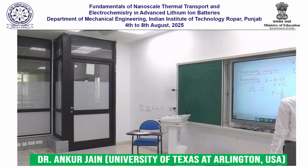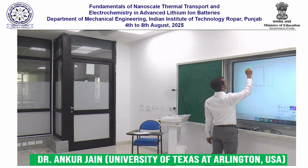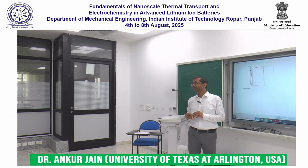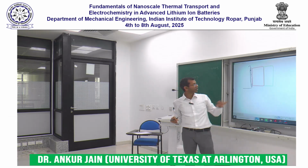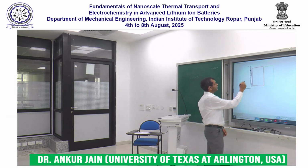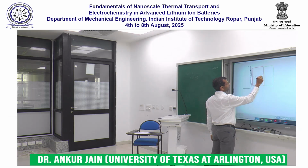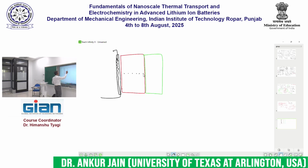So I will take a heater on this side and I will embed a number of thermocouples along the length, along the thicknesses of both materials. In other words, I will drill a hole and place a thermocouple here, here, here, here, here, and one as close as I can to the mating surface. And I'll do the same thing on the other side as well.